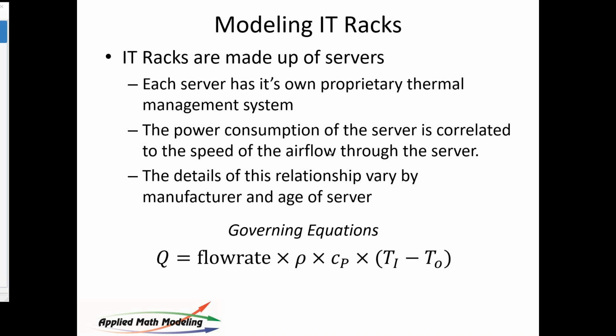So let's talk about IT racks and how they work. IT racks, of course, are made up of servers. Each server has its own thermal management system. I want to point out to you all that what we're doing in CFD software is trying to set up and solve a steady state equation for something that's really not steady state. These servers have their own thermal management system. The amount of air that they produce and blow is proportionate to sensors on it with a feedback control loop. The cooling unit is the same way. It has a feedback control loop. These units are not interconnected to one another and run on their own, so they often compete.